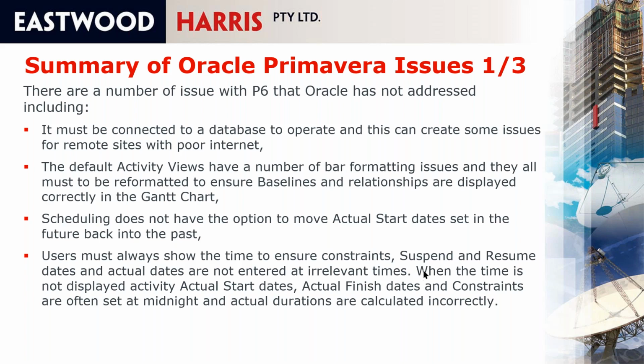It's really important that when the time is not displayed, you will find that actual start and actual finish constraints are set at midnight and the actual durations are calculated incorrectly. And it's a disaster. I've been in litigation where I've seen projects where all the actual starts and the actual finishes are at midnight, and I stood up and said, well, were you on site at midnight? They said no. And I said, well, the schedule hasn't been updated properly. This data and this schedule is irrelevant. So it's really important that people understand how to use P6.